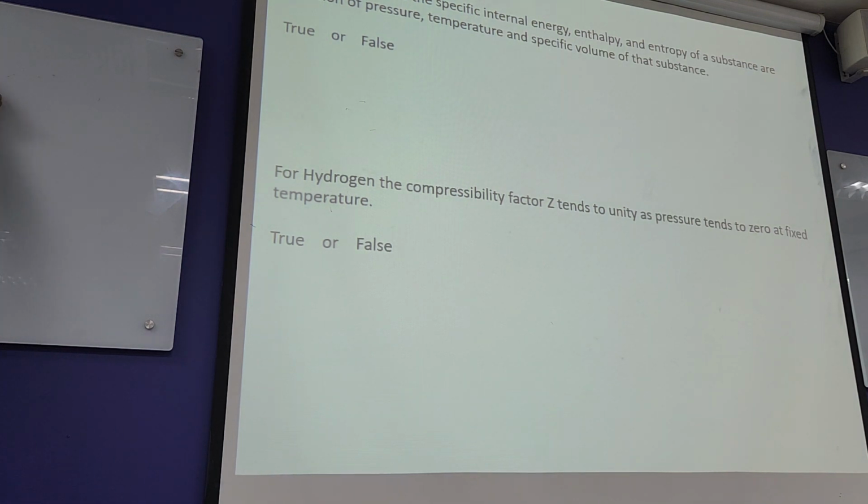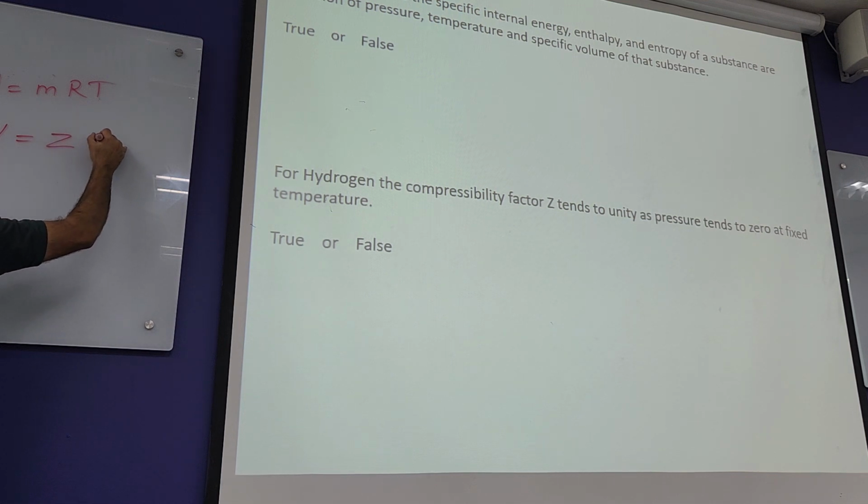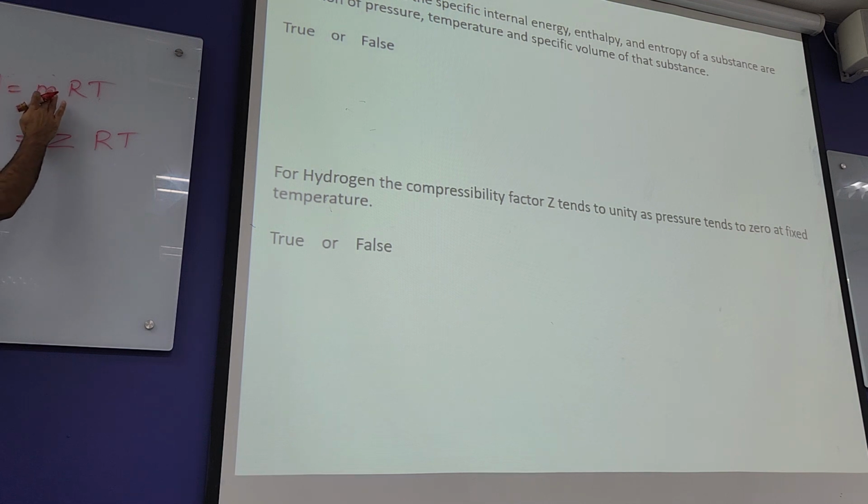So everyone knows that's the ideal gas equation, but you can use this ideal gas equation with a small variation for real gases, and that version looks like PV equals, and let me change that, keep that in there, and P small v equals ZRT, or P capital V equals ZMRT.